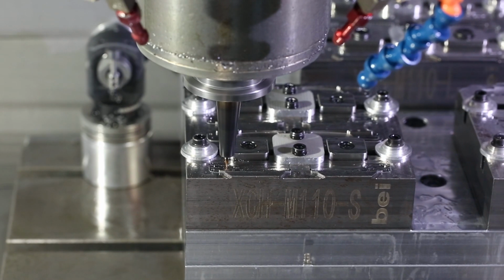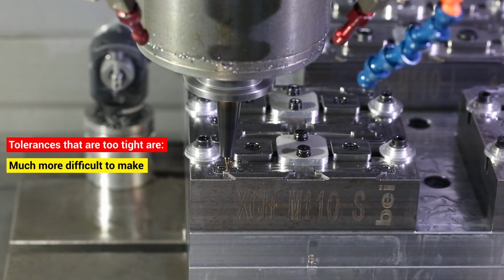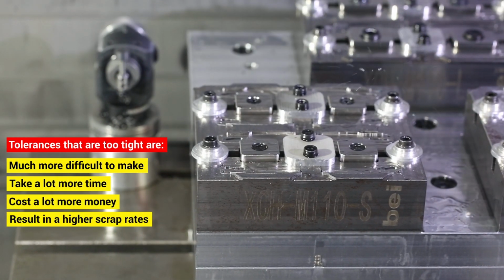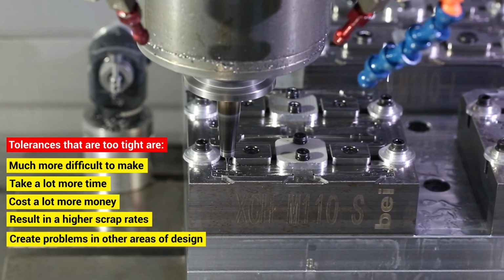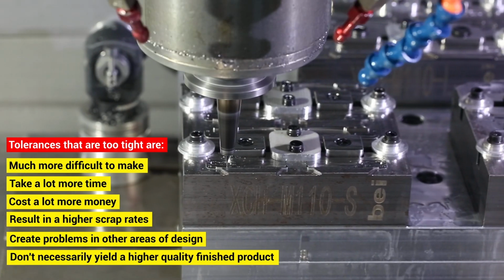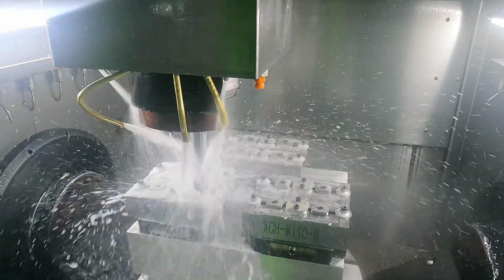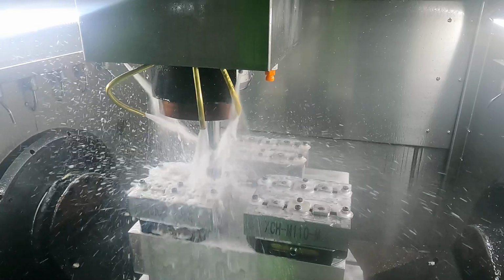But here's the secret we mentioned before. Tolerances that are too tight are much more difficult to make, take a lot more time, cost a lot more money, result in higher scrap rates, create problems in other areas of design, and don't necessarily yield a higher quality finished product. If you want to have a happy and stress-free life and get great parts fast with less expense and worry, then please heed this simple advice.